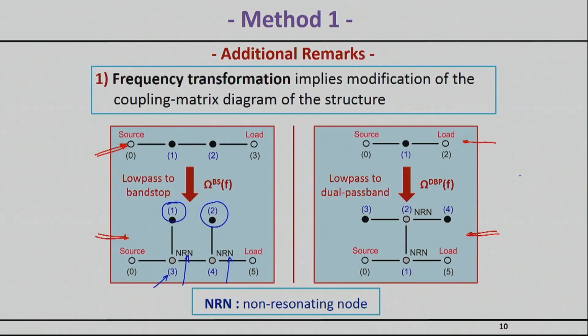They will not actually be resonators. So as you look at this coupling diagram, it's also important to realize why this thing implements a second order band stop function. So let's try to explain this. You have this guy right here, which when it resonates is an LC resonator that basically introduces an open, right? So this resonator rejects as an open. So at resonance, this thing is an open circuit.